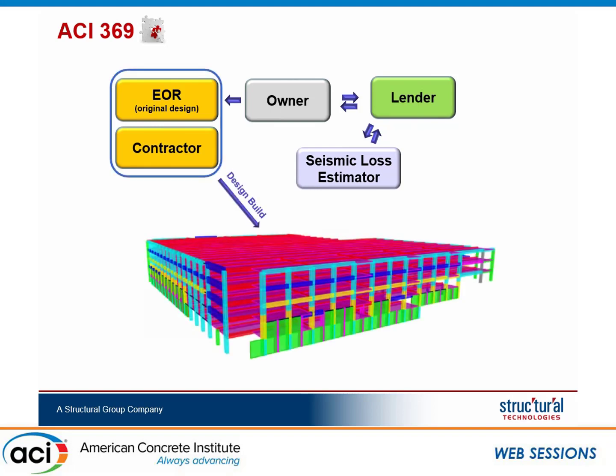My company took charge of modeling the buildings and performing nonlinear analysis on the 3 garage structures to establish where we need to fix these columns. Basically, using the ASCE 41 methodology, we established the roof target displacement. We looked at the demand on the columns at that level, and based on that, we designed the FRP.